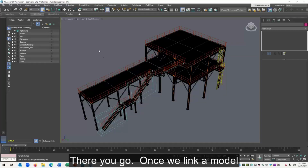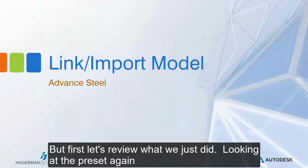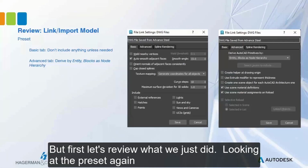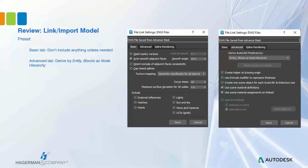And there you go. So once we link in our model, the next step will be to work on our appearance and get our view angle set how we want to see our animation. But first, I would like to review what we just did. Looking at the preset again, just remember on your basic tab of your preset, and I do recommend creating a preset for advanced steel models. You might have another preset for regular AutoCAD models. You might have a preset for Revit, etc.